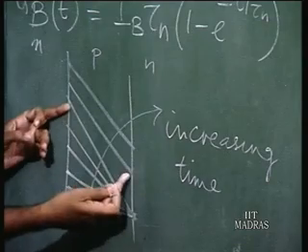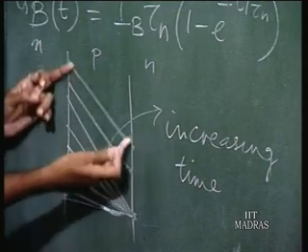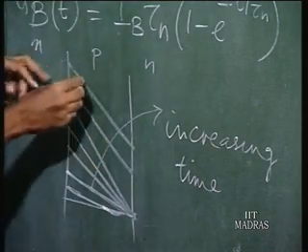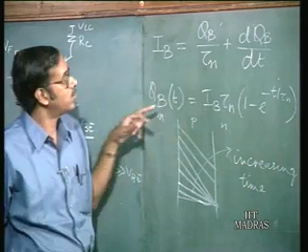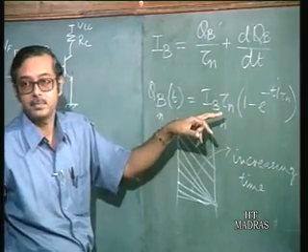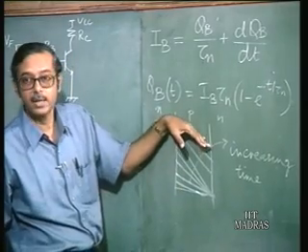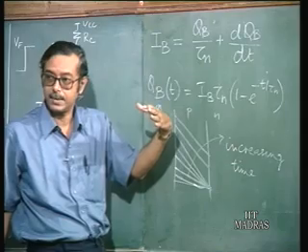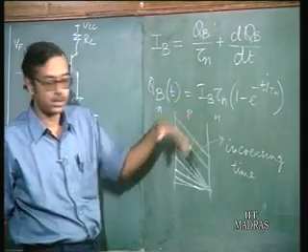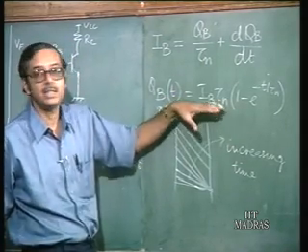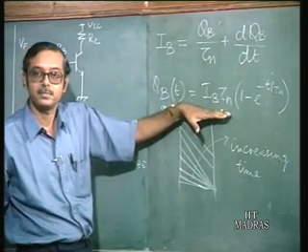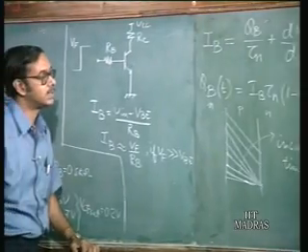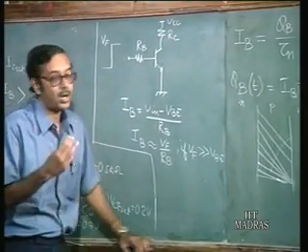So, you see that it goes up like this, all right, and this will go on increasing until the total charge stored here, okay, becomes equal to IB tau n. Finally, it will go up to IB tau n. Okay. The charge will keep on building up, although the transistor has reached saturation. Okay. It will not stop till you have reached IB tau n. Okay. Now, what we have to know is what time.